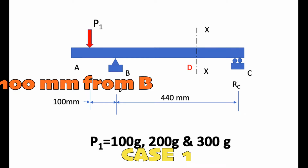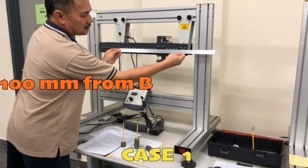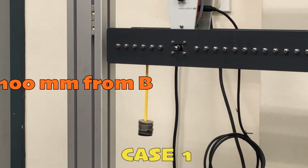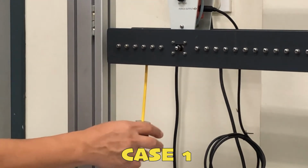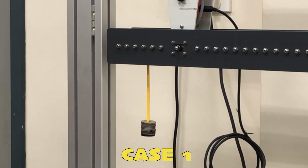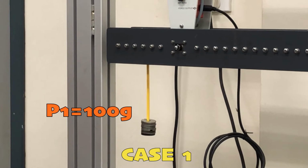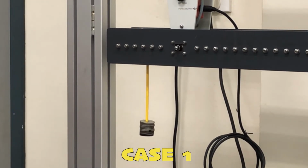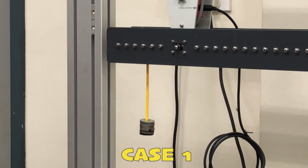For case 1, the first position is at 100 mm to the left from B support. The first load for this experiment is 100 grams, and when the beam is applied with this load, shear force happens at the cross-section XX, and it is displayed by the digital display.